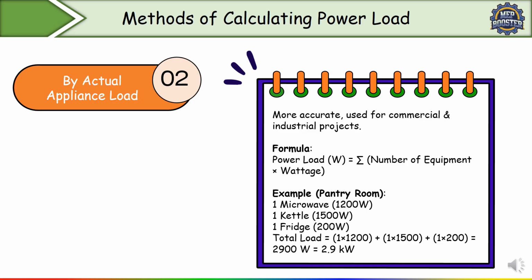Yes, am I right? But remember, not all power outlets in a large commercial space run at full load simultaneously. So demand factors are also used. If it is a residential application, we have to consider a demand factor of 40 to 60%. For office 60 to 80%, for commercial kitchen 90 to 100%, and for an industrial workshop normally 100%. I will explain the demand factor, don't worry.